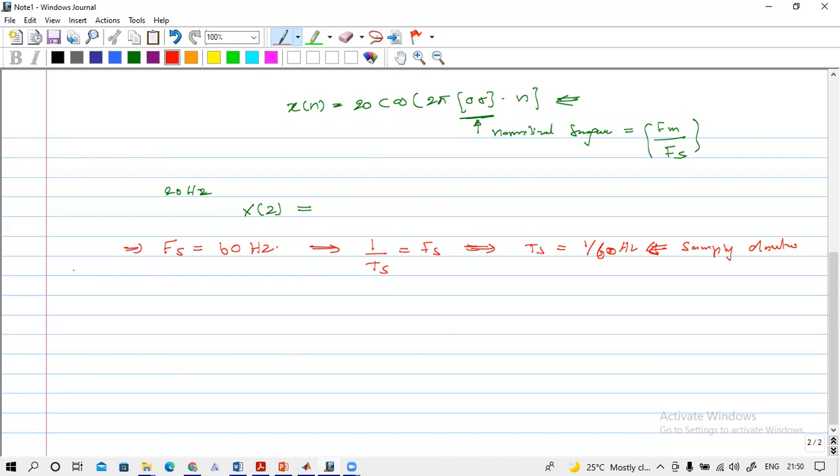This is the sampling frequency. Okay, so we have found the minimum required sampling frequency and maximum sample duration. Okay, so we will write it in terms of n, that means with the discrete variable. So you already know that t is equal to nTs. So to find x[n], we can directly substitute this value for t.